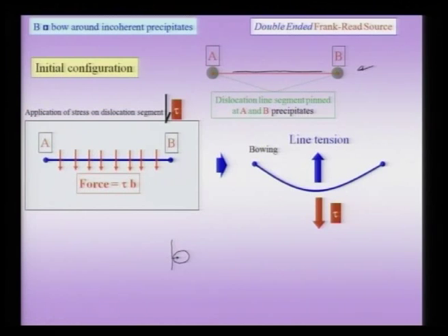There are no continuous planes. So, in other words, it is as if a different crystal is sitting across the interface. Therefore, the dislocation gets pinned at these 2 points, and it cannot move there. Now, suppose I apply an external shear stress. The stress would be felt at all the points along the dislocation line, and these stresses would tend to bow the dislocation as shown in the figure. But if I bow the dislocation, then the length of the dislocation line is increasing.